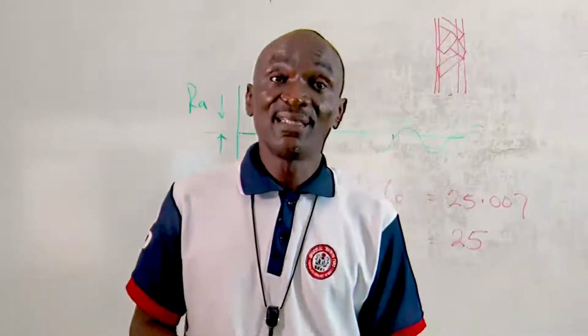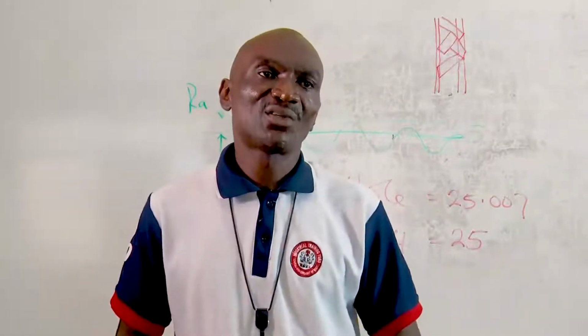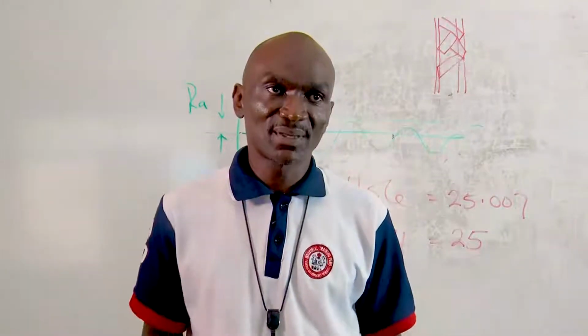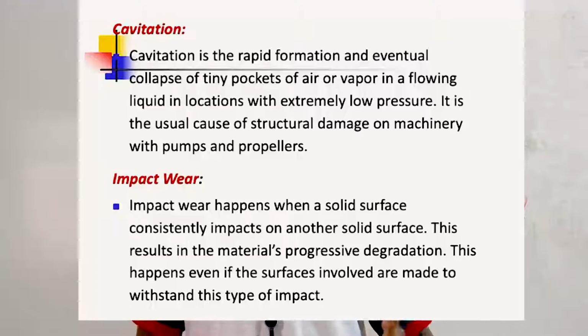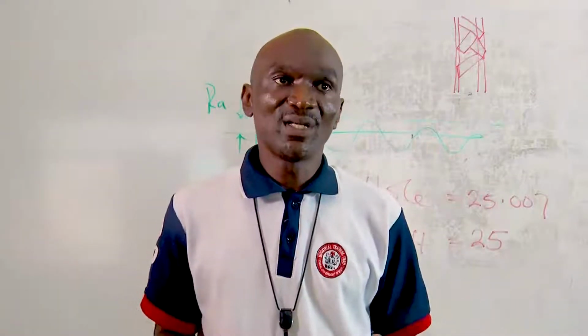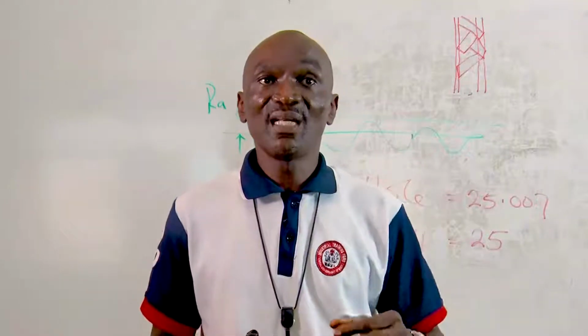Another cause of wear is cavitation. Cavitation is a very, very serious phenomenon when you are dealing with pumps, especially the impellers, the internal casing, and the internal components of pumps. Now, cavitation can be defined as the rapid formation and eventual collapse of tiny pockets of air or vapor in flowing liquids in locations with extremely low pressure.